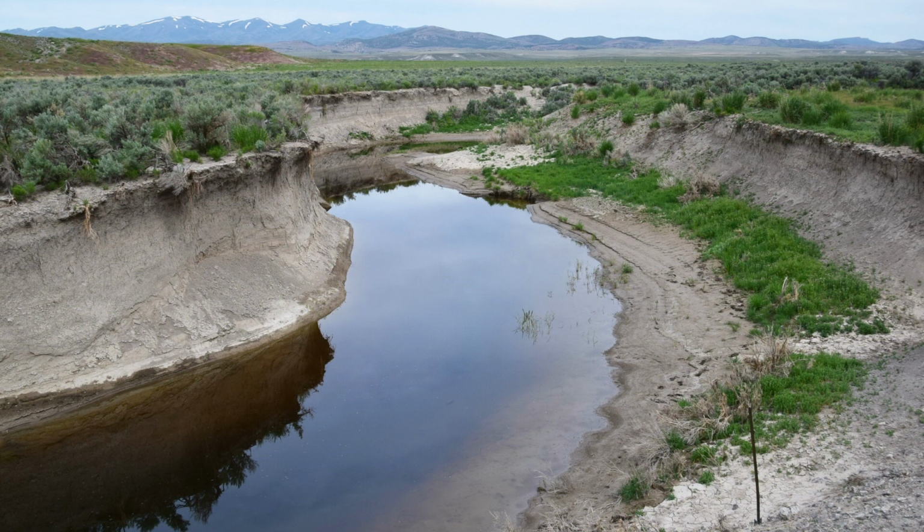This canyon is found within walking distance downstream of the wet meadow wetland. The canyon was formed by a progression of head cuts advancing through the wet meadow wetland. The water in the stream channel represents the elevation of groundwater. The water you see in the stream channel has been drained and pulled out of the historic wet meadow wetland.